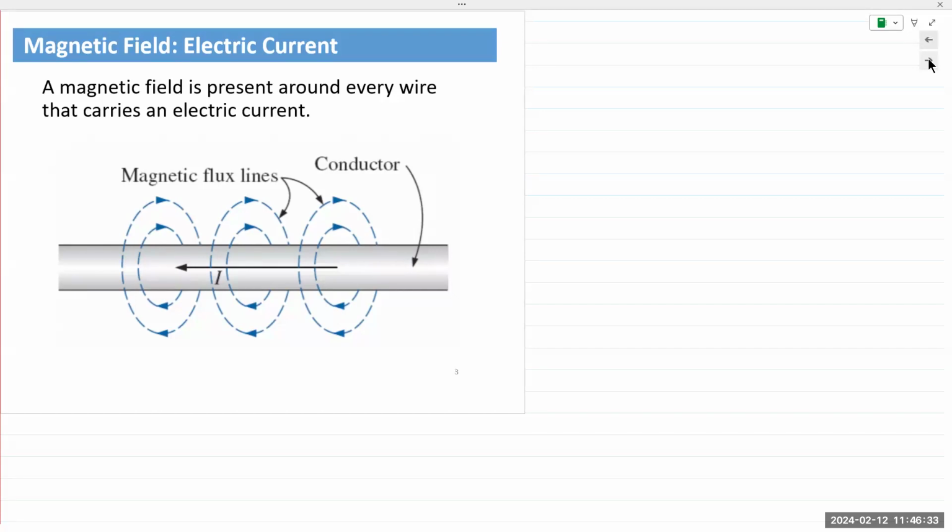If you measure the resistance of that long wire, it will have some resistance, a few ohms at most, but it does not rise to the level of interference. Its job is to transfer 120 volts from one end to 100 feet away. At most, that 120 volts may drop to 119 perhaps, but it does not interfere with the operation of our equipment.